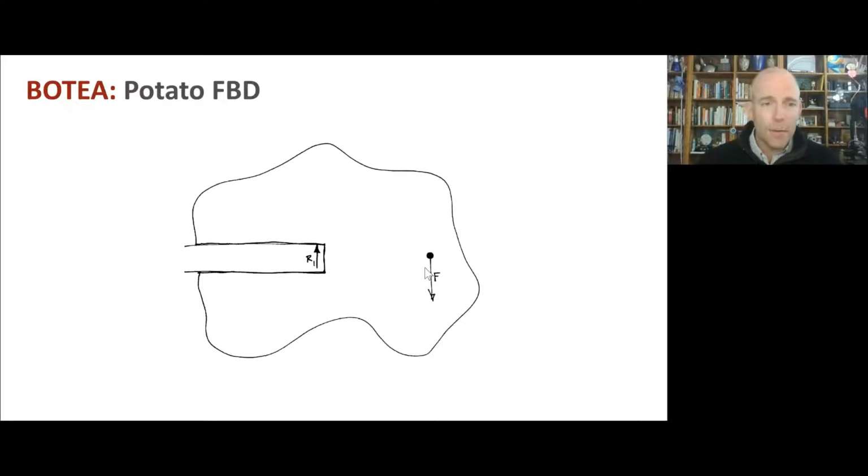And so we cannot bring those two things into alignment. Well, how will we get static equilibrium? We're going to need another force. For example, a reaction force downwards that is offset to the left of the upwards force from the table.